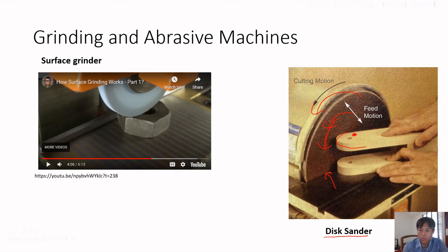That's why we need to put our material in this area. If we put the material in the other direction, then the force will be down to up, and that would cause the material to fly away from the machine. That's dangerous. So we should always put the material on the downward motion side.